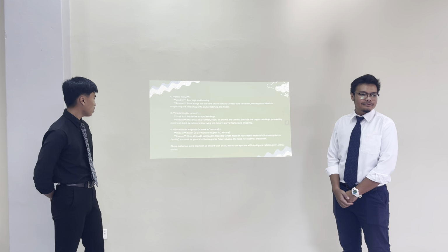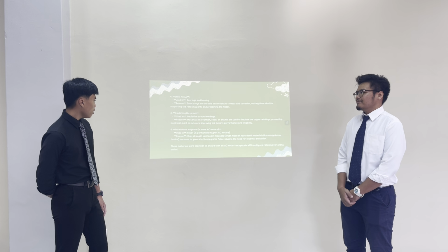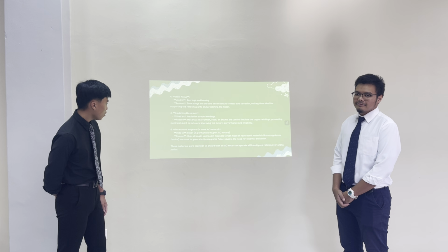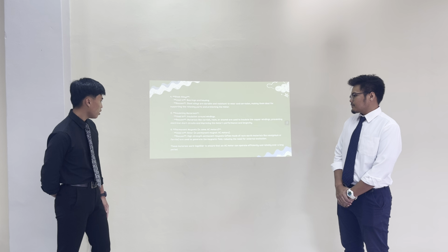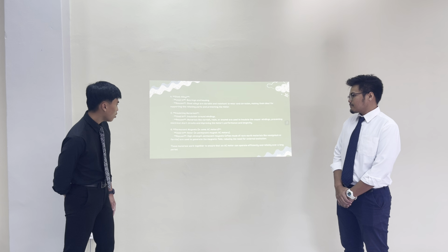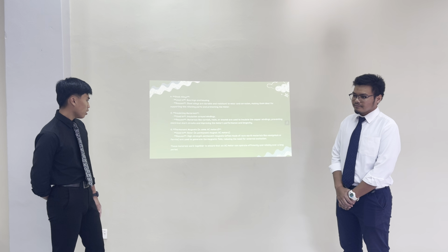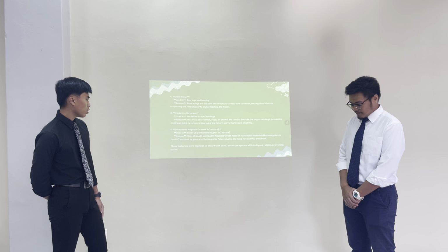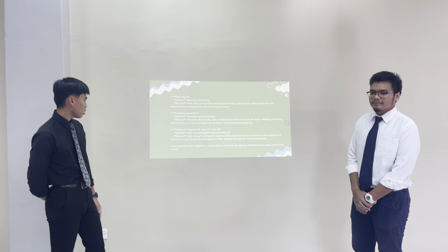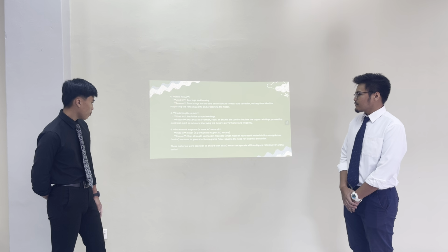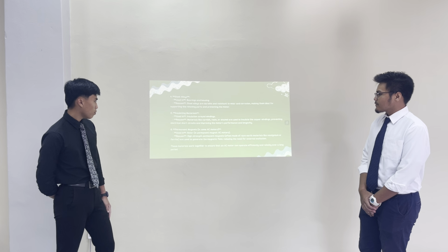Insulating material. Used in insulation around winding. Reason: materials like varnish, resin or enamel are used to insulate copper winding, reducing electrical short circuits and improving the motor performance.